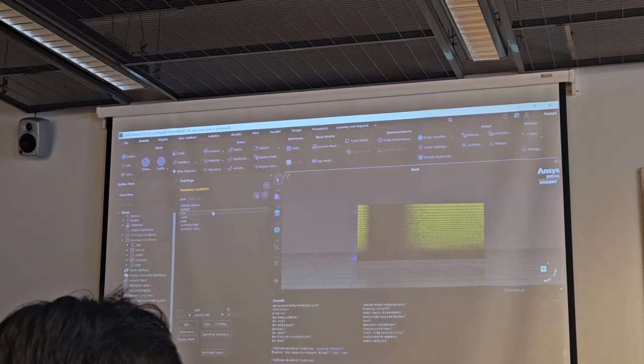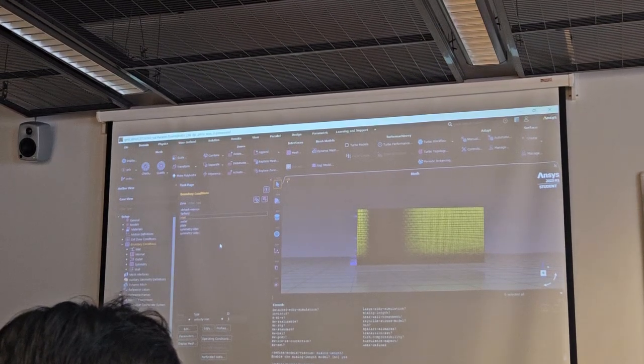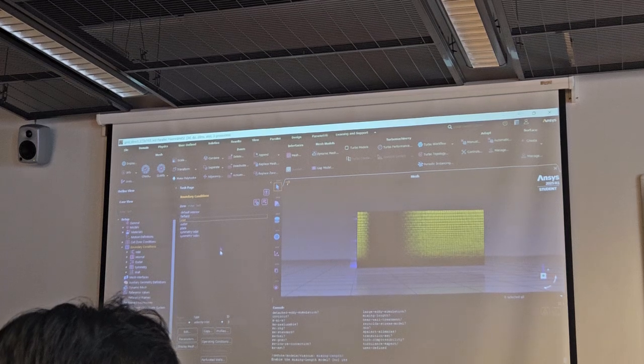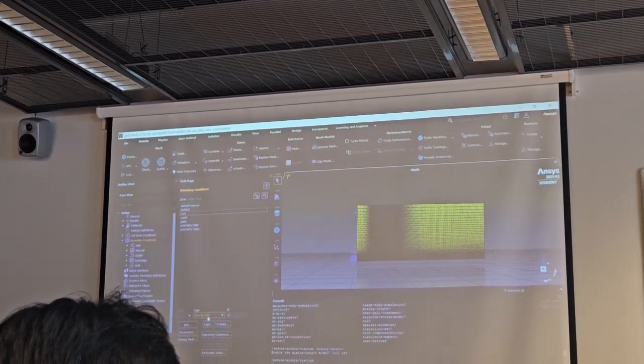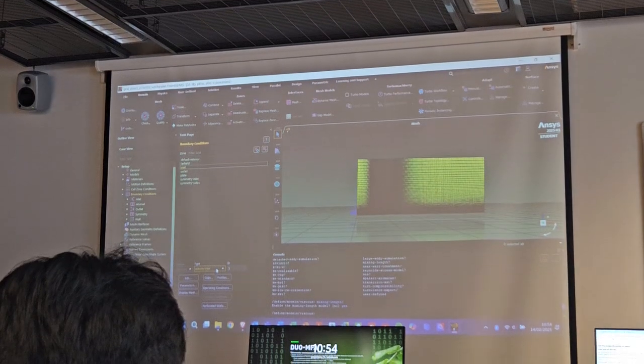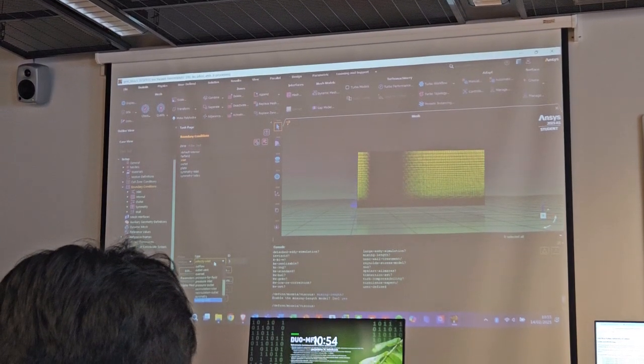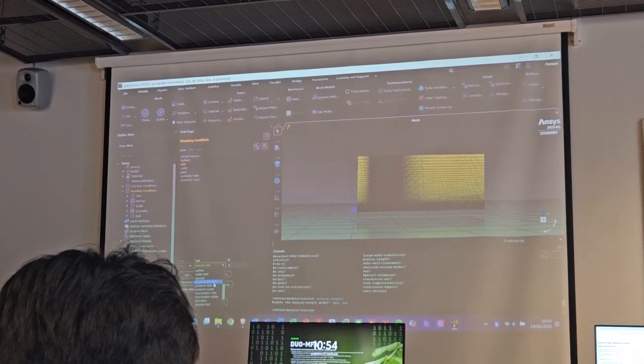Inlet. Here, we said we need to set total pressure and total temperature, so we need to change the type. On the bottom you have the velocity inlet type by default, and you need to change that to pressure inlet. You can see there is that option.